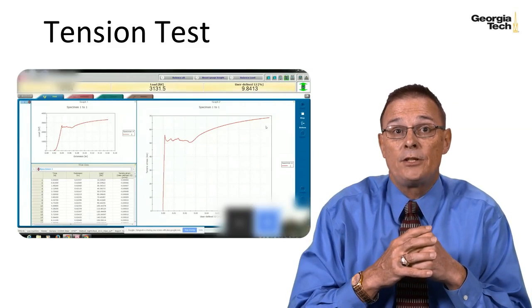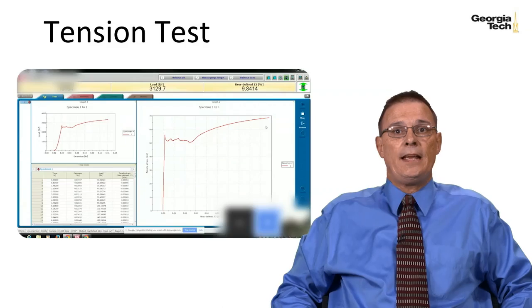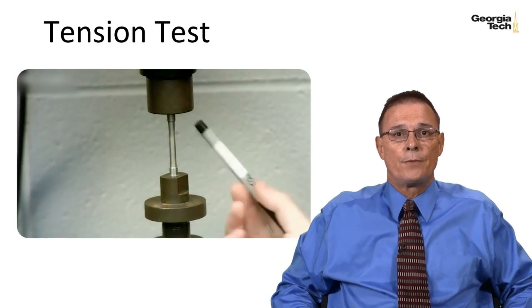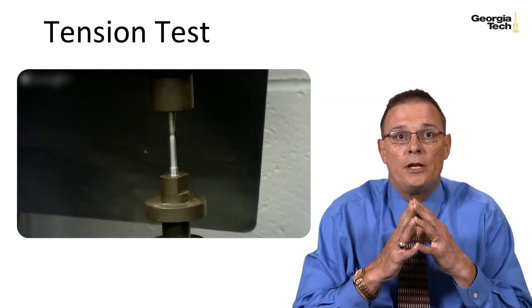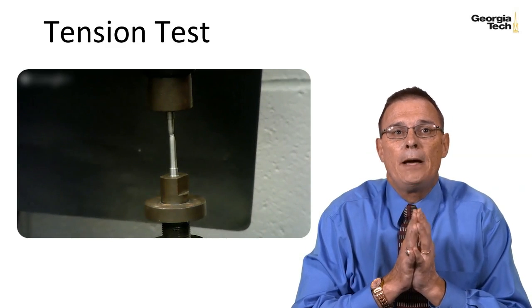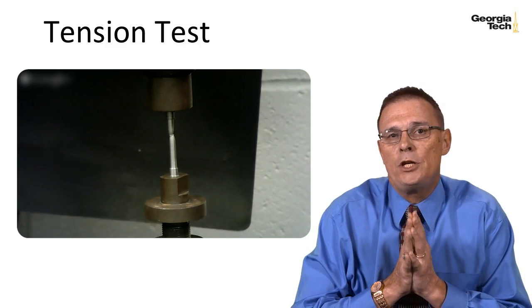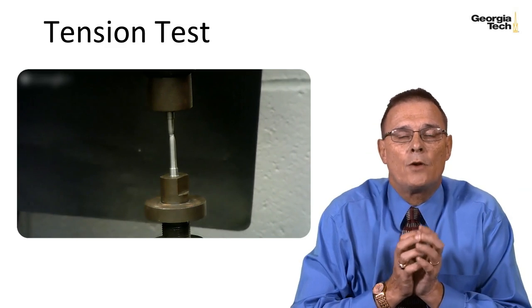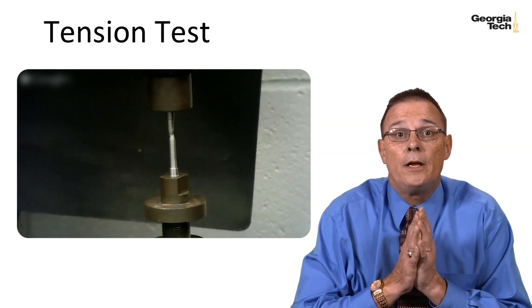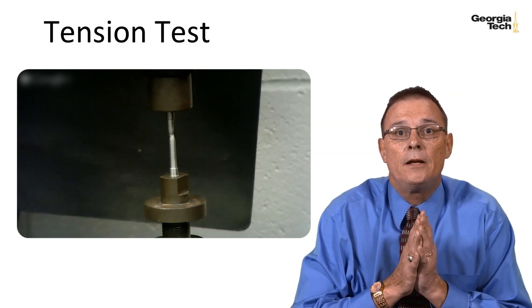As the specimen is continually loaded, you'll notice that it starts to neck down or become smaller in diameter until it finally fractures. The specimen used in this test is 1/4 inch diameter steel. It's classified as 1018 hot rolled steel. This type of metal is typically used for things like machine parts or shafts, like the drive shaft in cars. And steel is a ductile material, and we'll talk more about ductility in a minute.